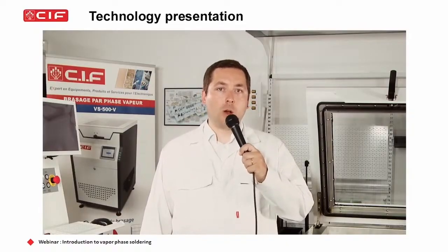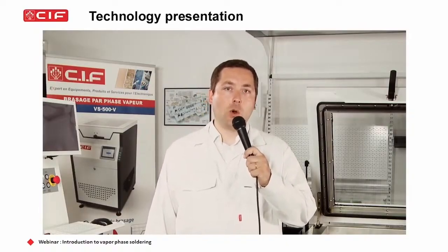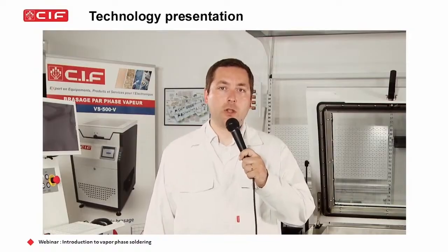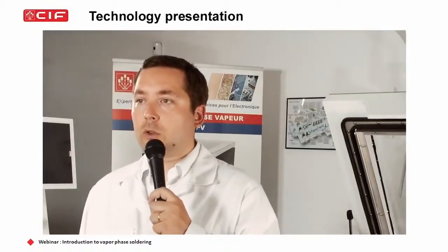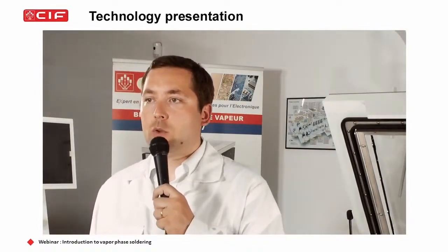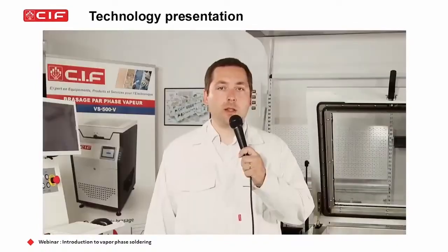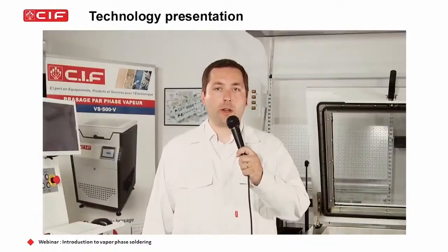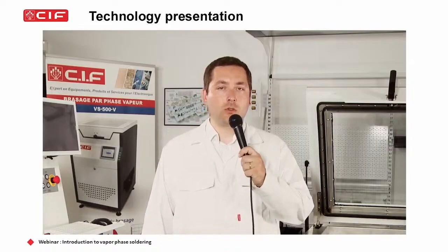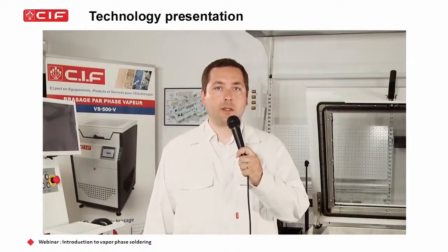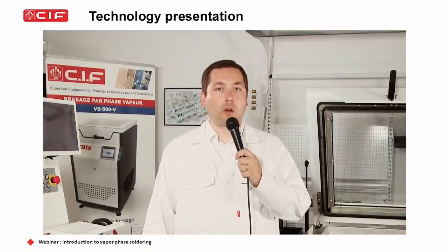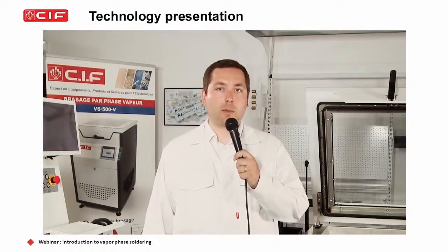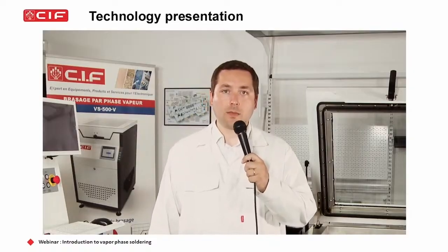Because you have a very low amount of voids and you have no oxygen blocked in your voids, it means no risk of oxidation in the future or too many voids leading to a weak solder joint. So it means you have very high quality solder joints, very stable electrically and mechanically. Even for power electronics applications, this is therefore a compatible technology.